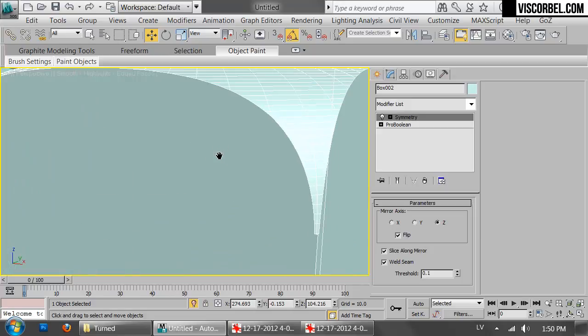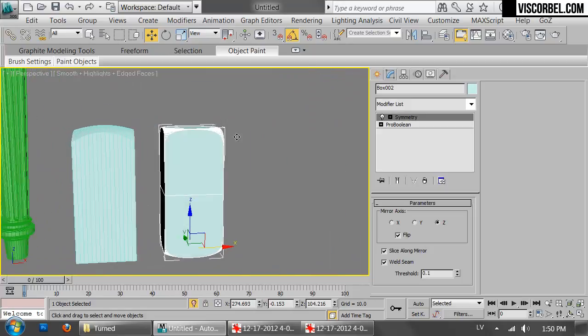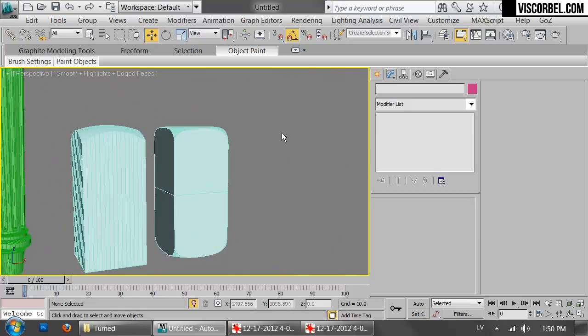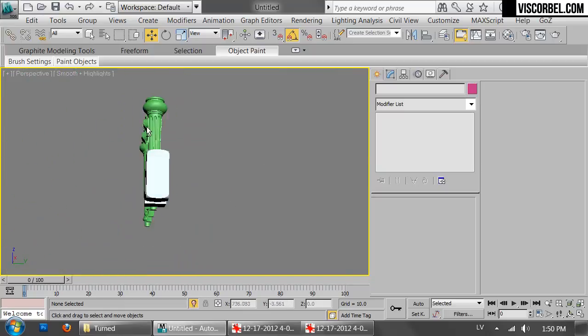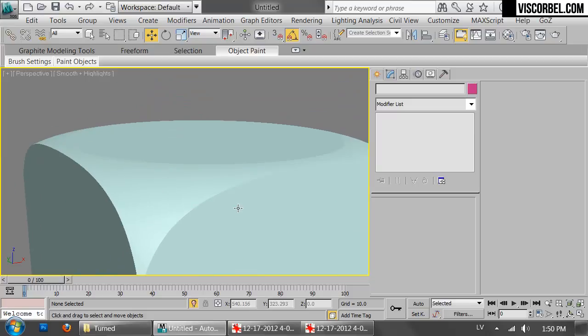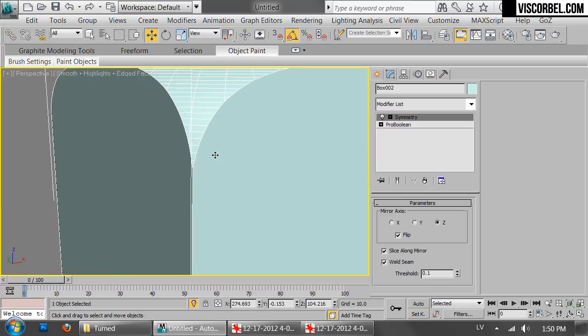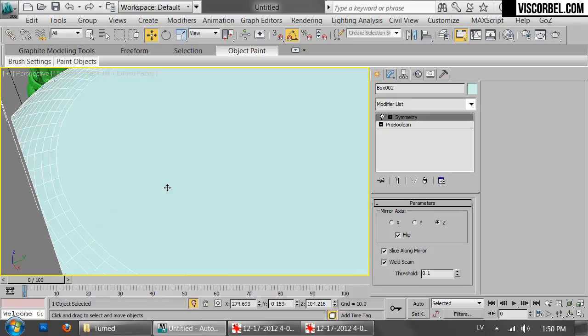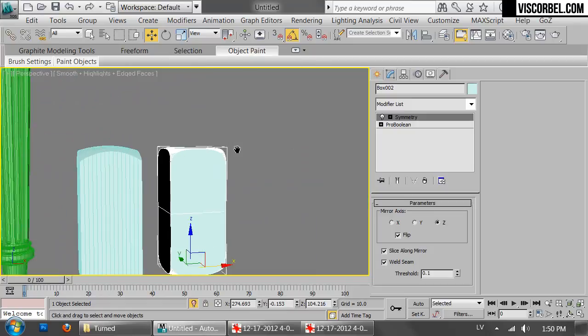Okay, and to get rid of these hard edges, you can simply use a VRayEdgesTex texture in the bump slot on your material or something like that, since these Boolean objects are pretty hard to modify with poly modeling tools.